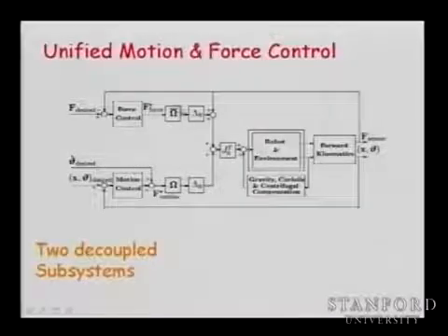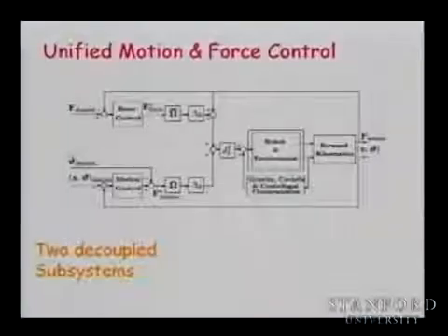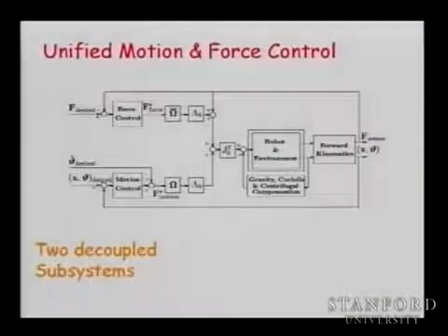Now what we are doing, we are projecting those controls in their spaces, and we are doing unified control of motion and forces. And because we are controlling everything in the task space, we have F motion, F forces, we just add them together. We have a total force that we transform into a torque through Jacobian transpose. And that is what is nice now. You unify all the characteristics.